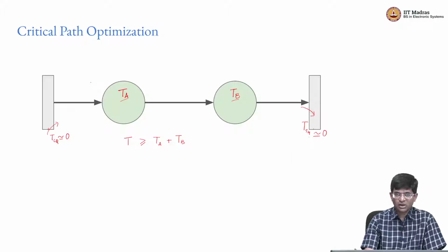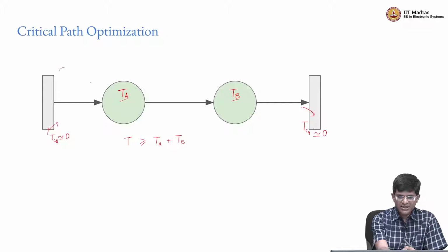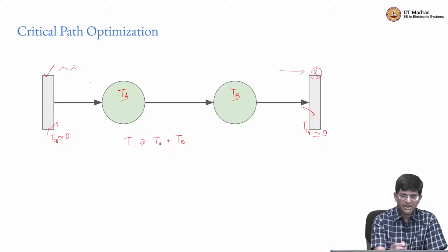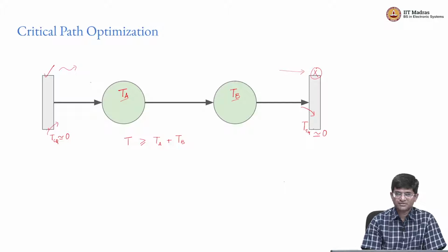Exactly at the same moment when the clock edge arrives on the second set of registers, we also assume that a clock edge is arriving once again on the first register, which means that new data is getting pumped into the entire circuit, right. So the way that it works is some data goes through this, some computation happens, it gets saved over here, and at the same time something new comes in from this register. So this is literally how we define clockwork or heartbeats or any kind of very regular event that's happening, and that's how all synchronous digital circuits are expected to work.